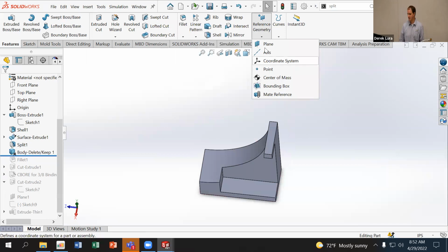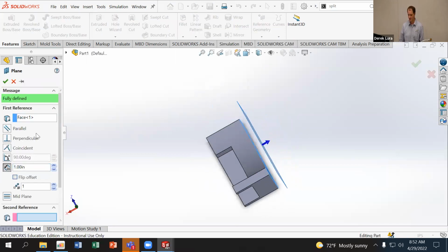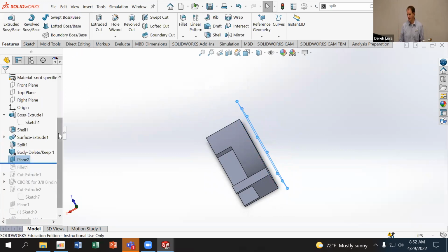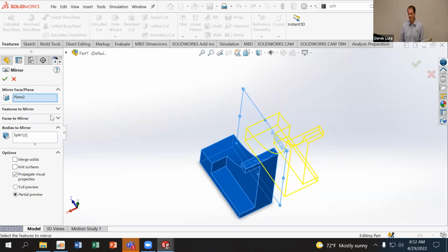And I make a reference geometry that's offset from this part. Say I want to have these two pieces, but I don't want them touching each other. Let's do, yeah, that's fine. I can mirror that body. Again, if I click on the body using my control options before I click on the mirror, then it knows I want to do a body. Again, I can't merge these together. If I try and click them, error, because they're not touching each other.